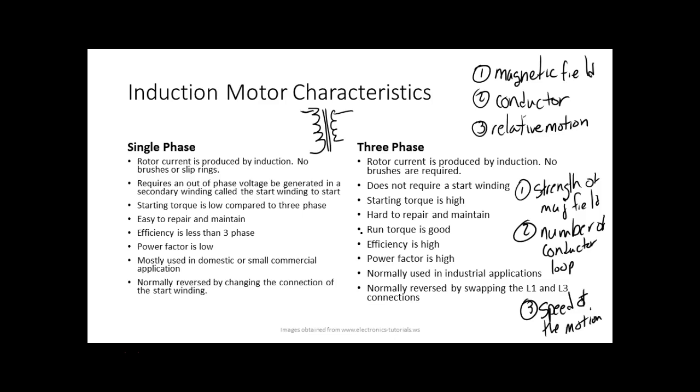They prevent the eddy currents from combining into one big current, which makes the core get very hot and inefficient. Most of our transformers are at least 95% efficient. That means if I get 100 watts out, I might be putting 105 watts into the transformer. So transformers are going to get warm because they're not 100% efficient, but they're pretty good.